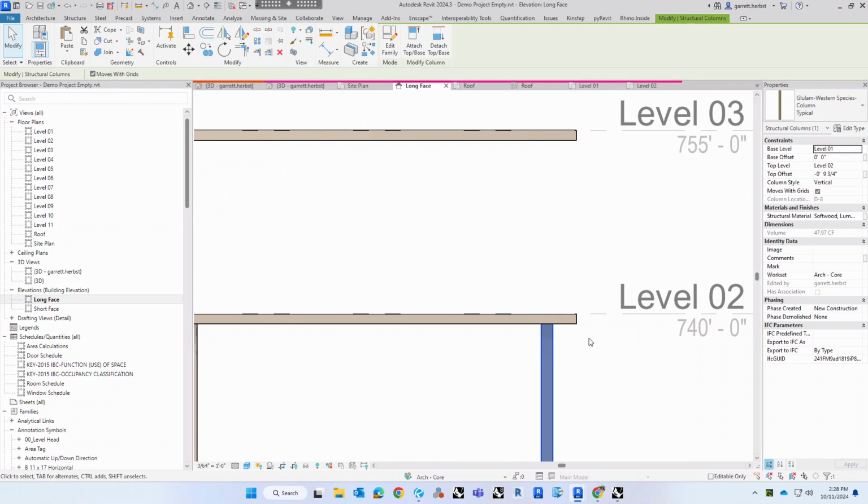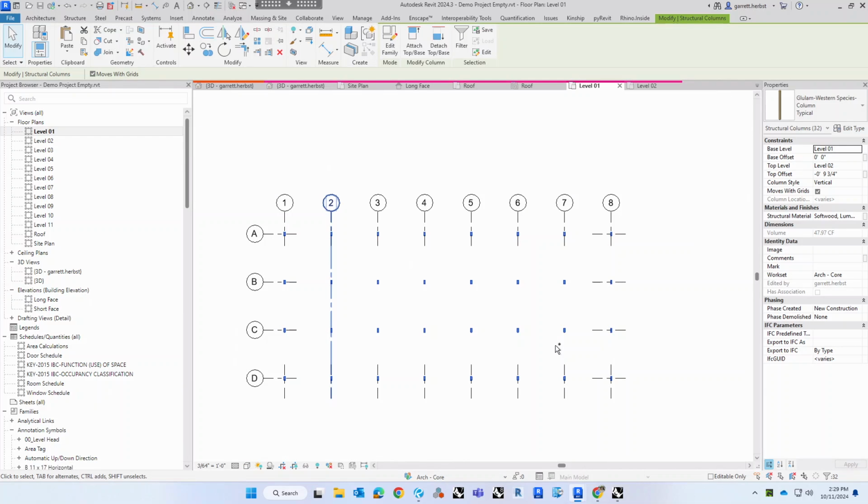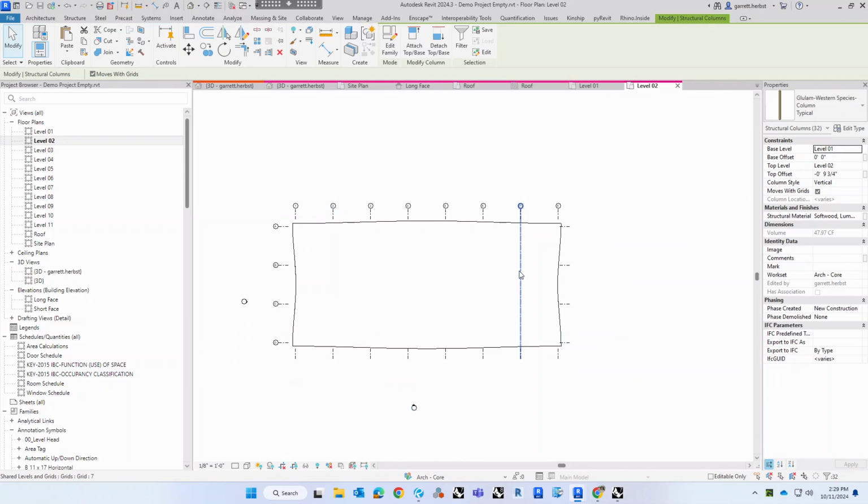Now, again, sometimes depending on your structural system, the columns will be going through your floor slabs. That's something y'all have to figure out. Remember that detail that Peter showed, where it had the connection that was actually going through the slab, and then the next column was connecting down to it. It really is up to how you want to model it, but that is up to you. So then once we have our columns, now I'm just showing the same size column everywhere, but of course in real life, the columns would start off larger and then get smaller as you go up.